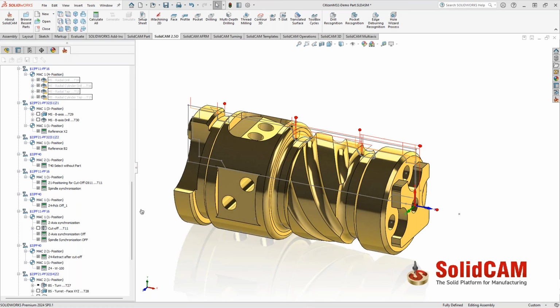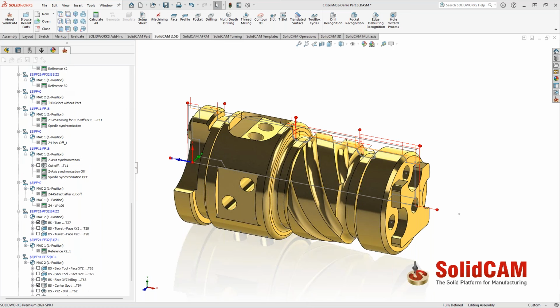We're going to jump inside the MCO. Now, what is all this about? Whenever you define an extension collet, depending on the machine brand, whether it's a Citizen, Star, or Tornos, these extension collets are not calculated points on the machine, meaning every time you make a part transfer, they consider that the face of the spindle is the relevant point for the part transfer.